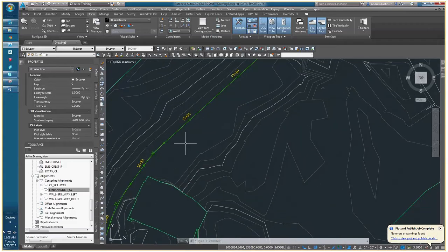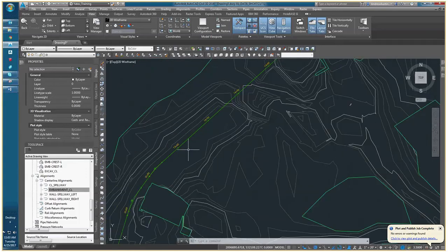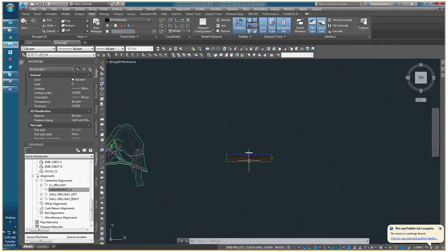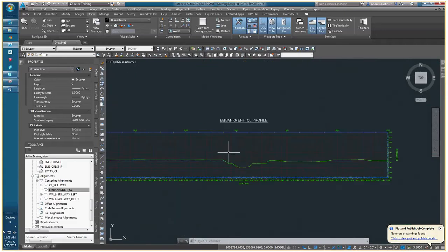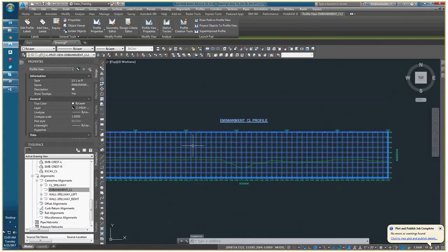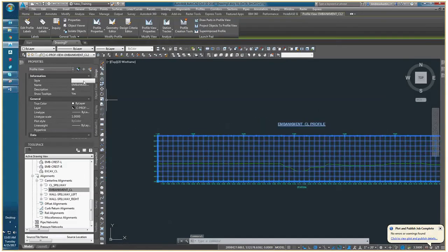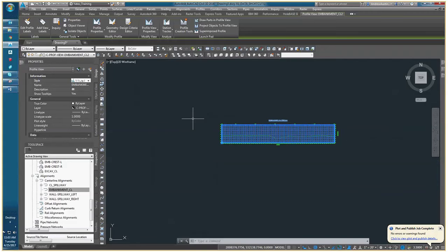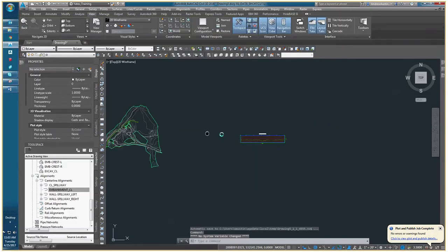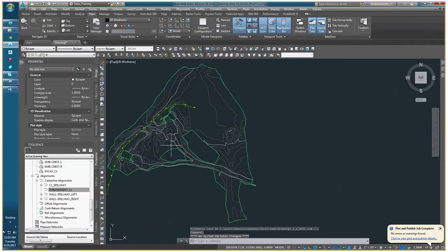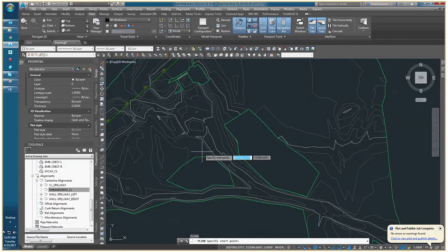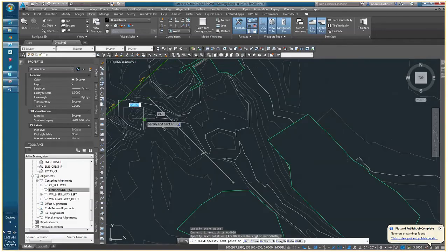And that is actually fairly critical when it comes to flow directions and how sections and other things are cut. For instance, when we plopped down this profile view, it had a very specific style associated with it. That style is known as 1-to-1, left to right, L2R. Okay? And so it's displaying this profile view as if we were looking at a section, or a cross section of this existing site from this direction.